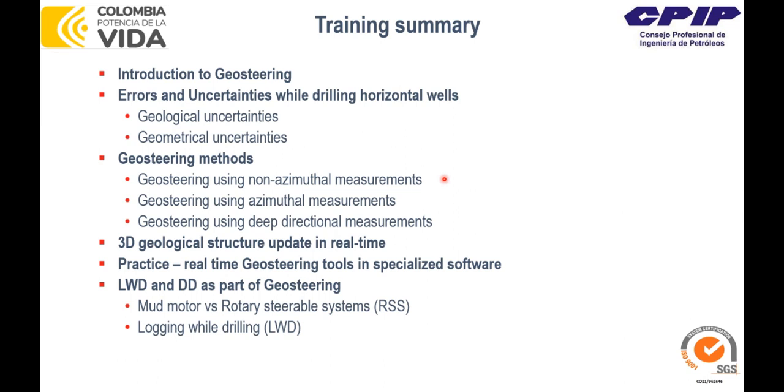For more advanced BHAs, we can move to azimuthal measurements, the azimuthal curves and azimuthal data for density, gamma ray, and resistivity, and we can generate borehole images, a very useful visualization of the borehole cylinder laid down, and we can pick up the formation dips. We can calculate the angle of the dips, as we learned in the practice with the software, working with the images.